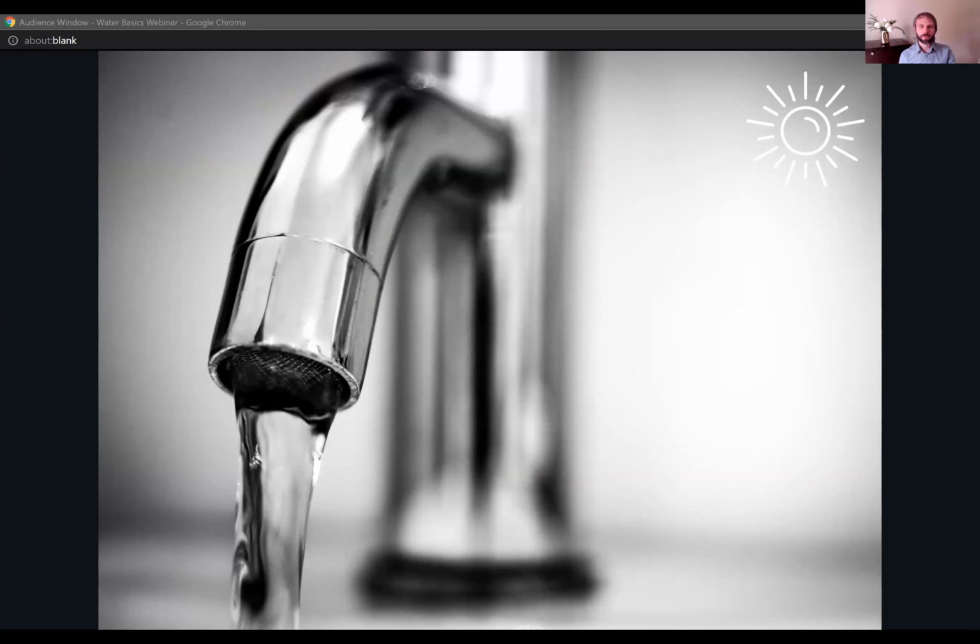Next up are faucets. So bathroom aerators, bathroom faucets, kitchen faucets. On the bathroom side, we're looking at around 2.5 gallons per minute, GPM, 2.2, 2 starts kicking in for the green building programs, 1.75, 1.5, 1 gallon per minute. 0.5 is kind of where we really like to see these aerators, and you don't even notice the difference if you've got correct water pressure. And then we've even seen some down to 0.38, believe it or not. And whether those work or not is to be determined.